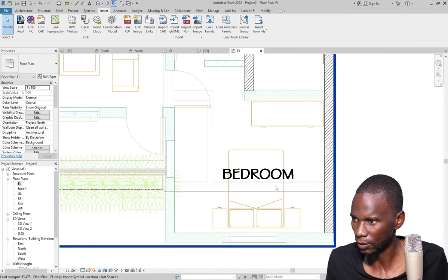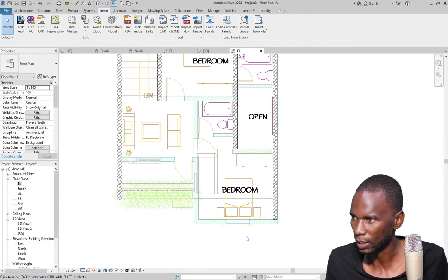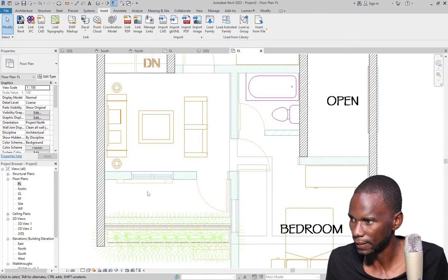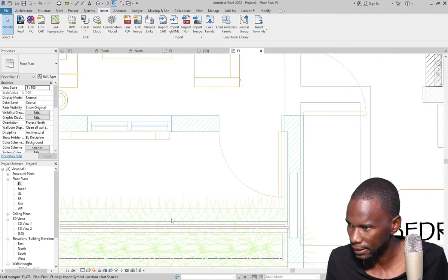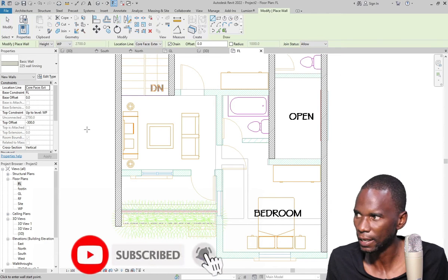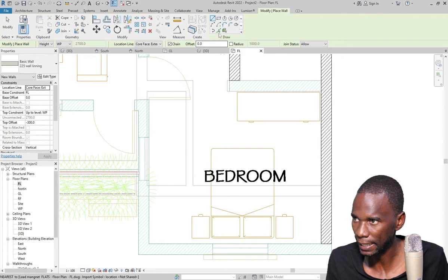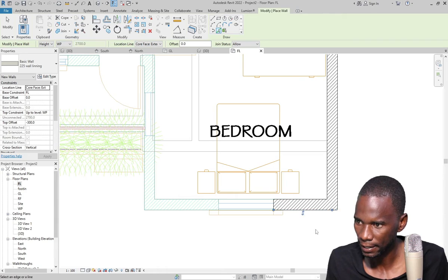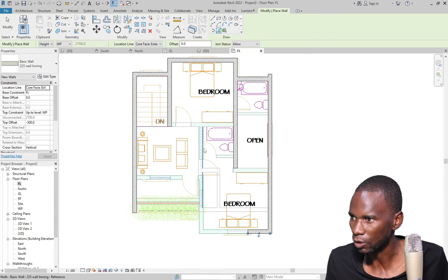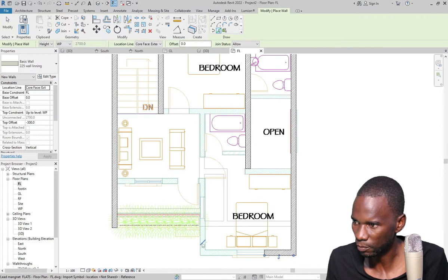And you see that I don't need these walls in between, but I'll need this one here. So what I'll do, I'll simply select this wall, right click, create similar. Now I need to check the height, meaning that I'm starting from this level up to the wall plate, okay? So I need this wall. Let me just use pick lines there, then pick that one. I also need this wall. If I want this one, I can extend the one from the ground there.